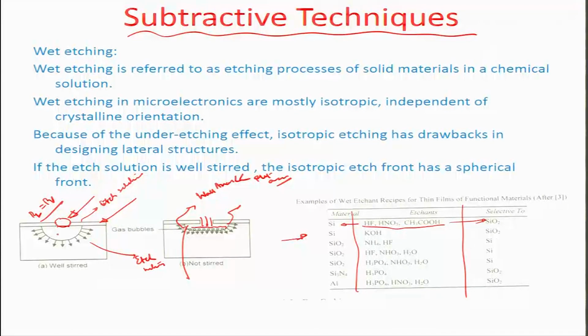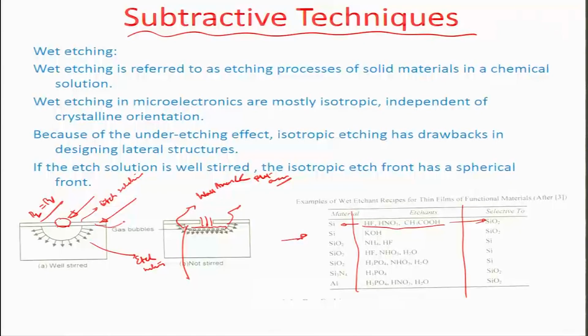So, if materials are removed properly, then undercut probably happens in a homogeneous manner, but if it is not removed properly, then undercut happens in a very skewed manner, and obviously whatever size or domain you are etching, the overall etch profile that will eventually come out will be higher in width than the planned etching zone. So, therefore, masks have to be designed in such cases, and by masks I mean this particular etch selective layer.